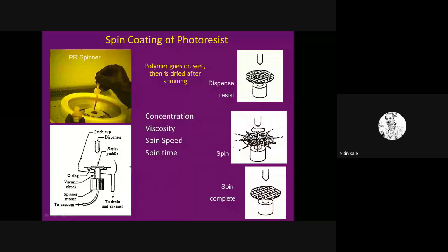Here it is important that the humidity of the chamber is controlled, because at very low humidities the photoresist will tend to crack, because solvents tend to escape from the photoresist. And at high humidity, the adhesion between the photoresist and the wafer is going to be poor, because photoresist is a polymer and humidity is water, so there is a dislike between the two.